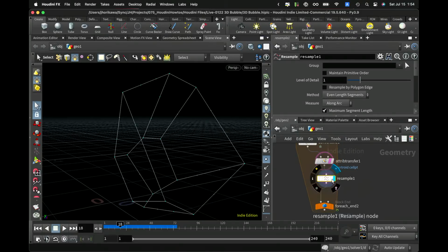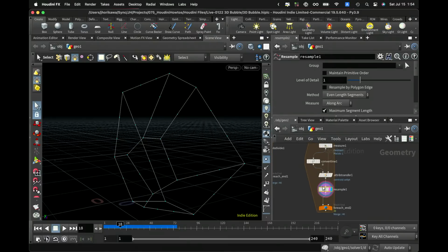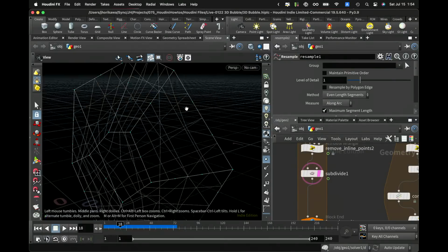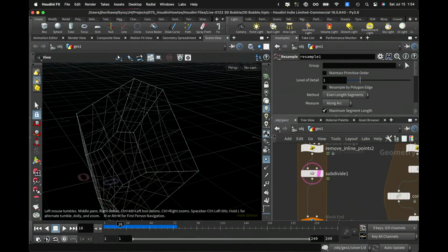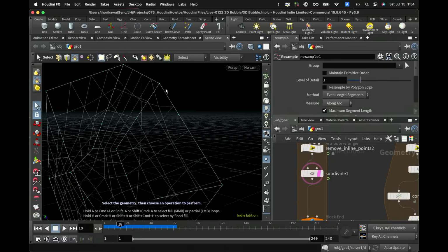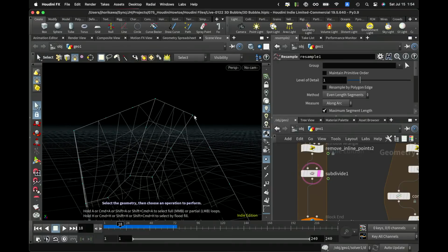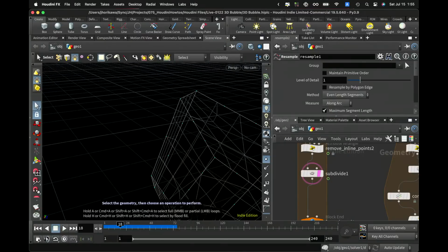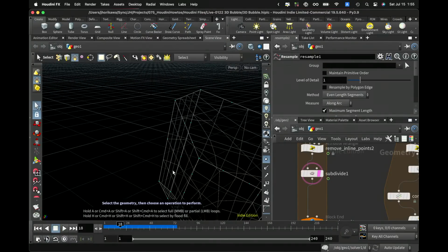Now this resample is pretty important, and the number of points you add on each line has to be the same as the position of this subdivide mesh. So for each subdivide mesh on each edge, in this case you always have 1, 2, 3, 4 divisions. Even with these small lines, you have 4 divisions. 4 divisions here. On the side, you also have 4 divisions.